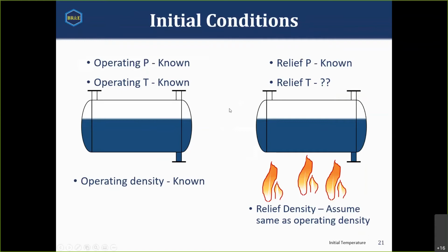Density is equal to mass divided by volume. If I have not let any mass in, if I say our relief valve has not opened yet, the mass in my system before the fire and after the fire are the same. I'll say that again. If I'm not letting any mass into or out of my vessel, the mass in my vessel has to stay the same.